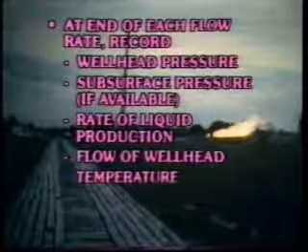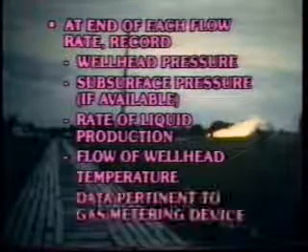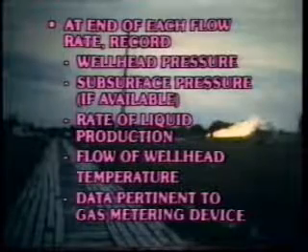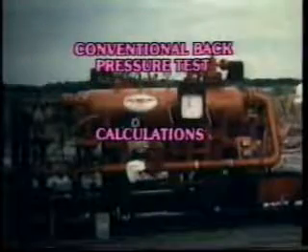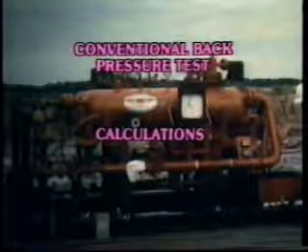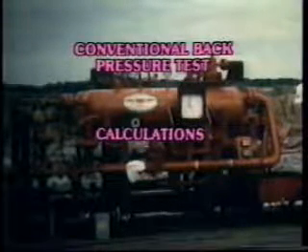At the end of each flow rate, the following data is recorded: flowing wellhead pressure, sand face pressure, rate of liquid production, flowing wellhead temperature, all gas metering device data. The complexity of calculations depends on whether a back pressure equation based on wellhead or sand face pressures is to be used.